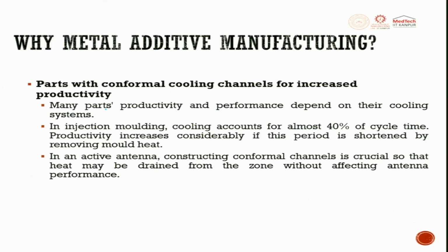Many parts' productivity and performance depend on the cooling system. Your laptop also depends on its cooling system. Injection molding cooling accounts for about 40% of the cycle time. Productivity increases considerably if this period is shortened and heat is removed in a quicker way.